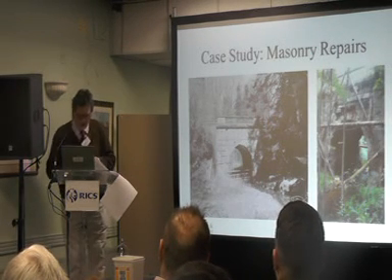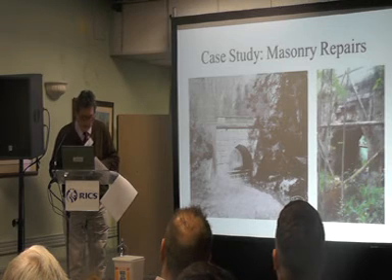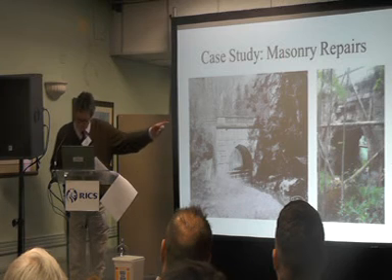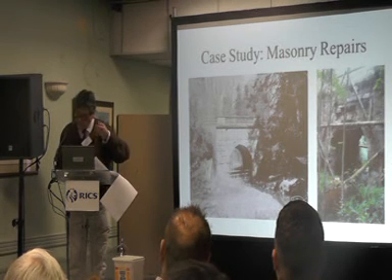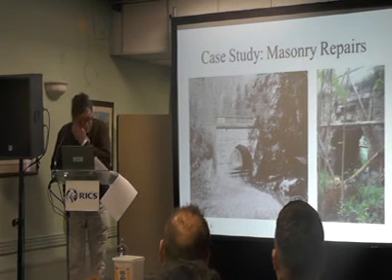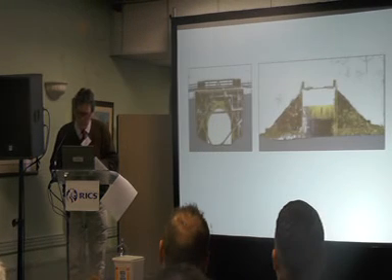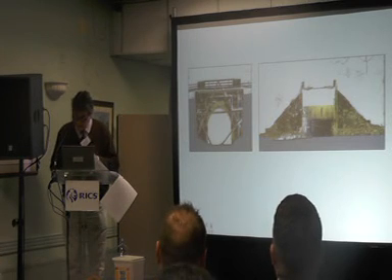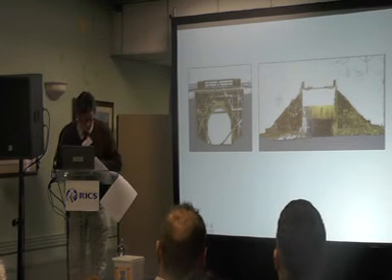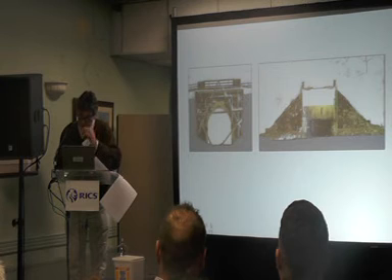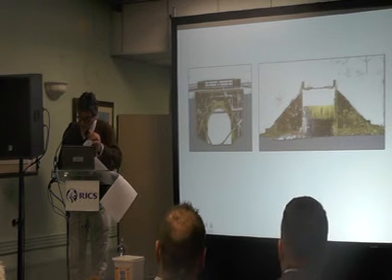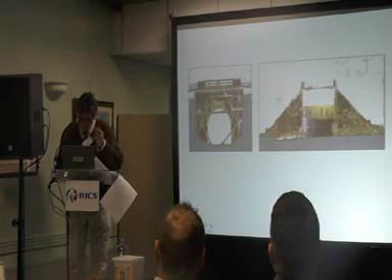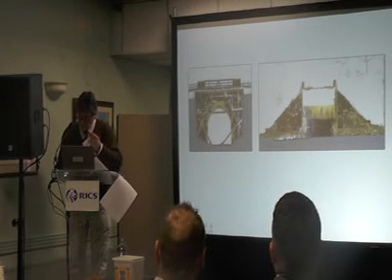Right, case study. This is a bridge, also said to be by Adam. The photograph, black and white, taken in 1963, the colour one taken a couple of weeks ago. It's like a Christmas cake with all the icing falling off into the water. Now, what we've done is we've scanned this bridge in 3D to a very high resolution, less than a millimetre. So every aspect of that bridge, every stone, every mortar bed, every defect is scanned, and we have a point cloud, a very dense point cloud, which is a digital jelly mould.